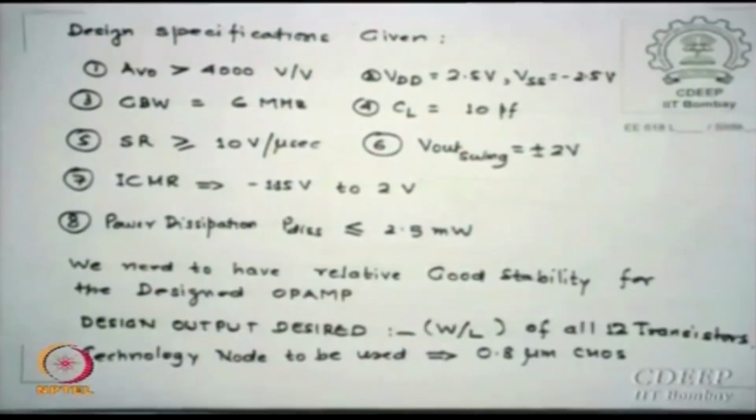Alternatively, you evaluate all the values without CL by the formula we gave and add the external CL value and say that is C2 now. Okay. That okay. For evaluation right now some number is chosen which is high enough compared to others. We are also told the minimum slew rate should be 10 volt per microsecond. That is the output voltage should rise up to 10 volts in a microsecond, okay, that is called slew rate. So dV0 by dt minimum required is 10 volt per microsecond.